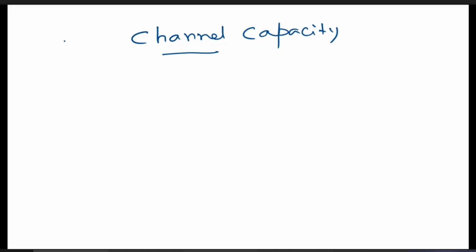It's also called white noise, and it is significant in the case of satellite communications. And we have seen how noise can be estimated for a bandwidth of B. It is kTB. So in terms of dBW, you can find it out. General problems are there. You must take care of all those things.